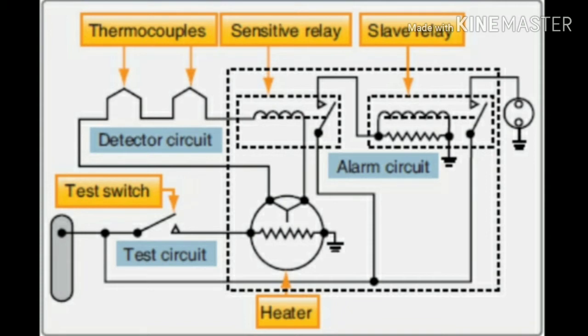It could be an early warning of fire and would alert the crew to take appropriate action to reduce the engine compartment temperature. The second level response would be at a level above that attainable by leaking hot gas and would be the fire warning.